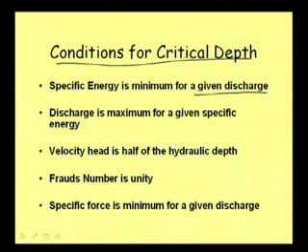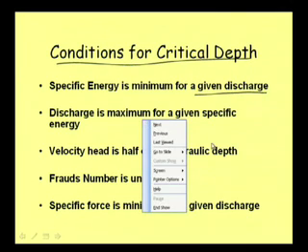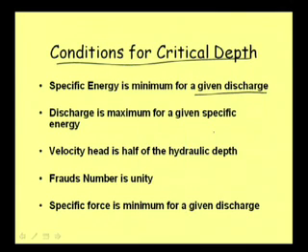Second condition, as we could see, the discharge is maximum. Here, when we say discharge is maximum, we need to speak about discharge being maximum for a given specific energy. This is also important. When we talk about the first condition, we need to mention it is for a given discharge.